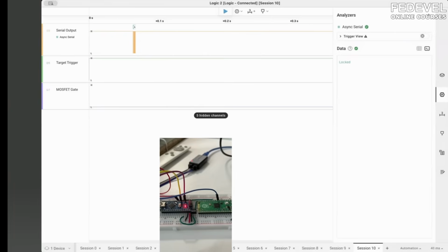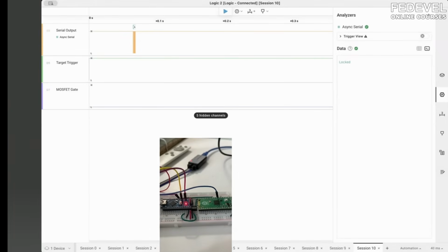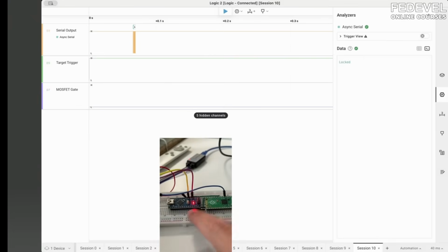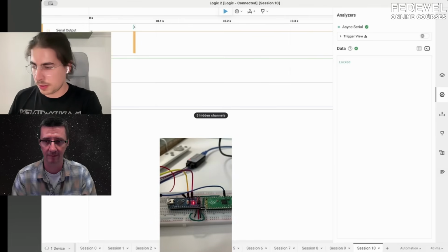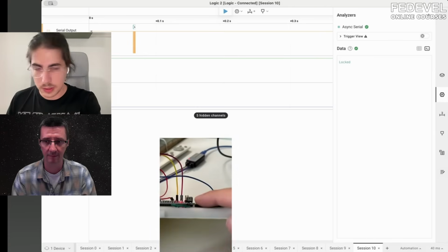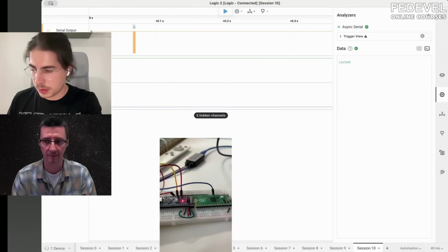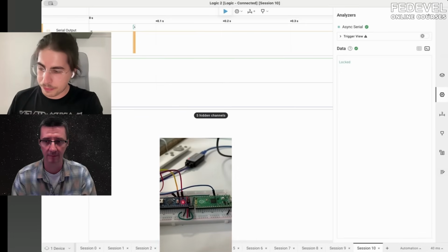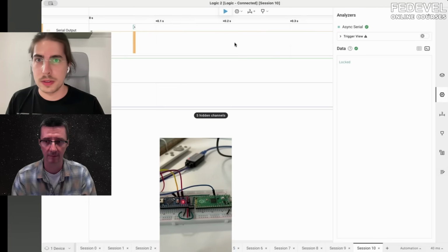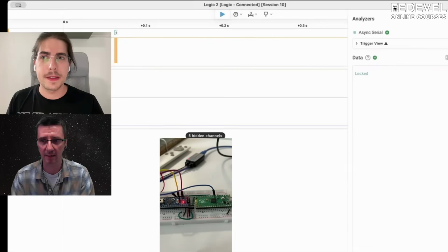What we see here, first of all, in the camera, we have a target, which is this blue chip. Lots of you will know it. It's an Arduino Nano, and it's running a firmware that's counting up to a certain number. And we want to show how easy it is to change control flow with a simple MOSFET that's just plugged into the breadboard. So everybody can do this at home. And by performing a hardware attack, a voltage fault injection attack, we can change the number that the code is calculating.